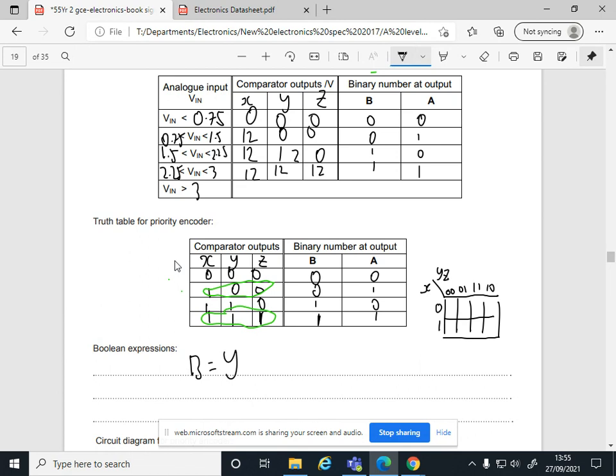Okay, so you could look at that and look for unique things. However, if you're unsure, use the old Karnaugh map. So I'm going to put this into the Karnaugh map, to be honest. So let's have a look. At location 000, I put a 0. At location 100, where X is a 1, I need to put a 1. At location 110, I need to put a 0. And finally, at location 1, I put a 1. All the rest become don't cares.